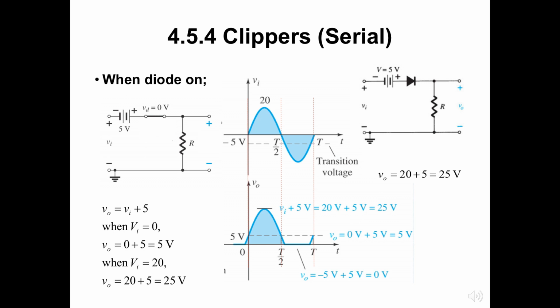In middle figure a horizontal line is drawn through the applied voltage at the transition level. For voltages less than -5 V the diode is in the open circuit state and the output is 0 V, as shown in the sketch of VO.